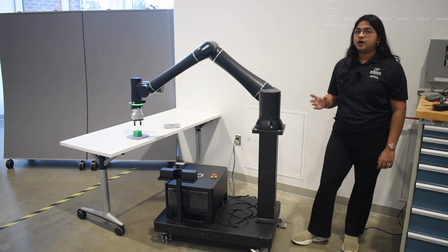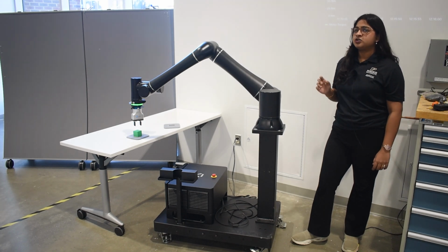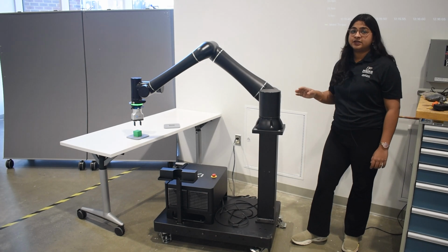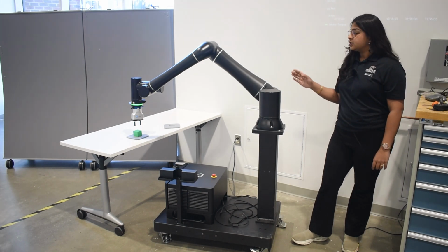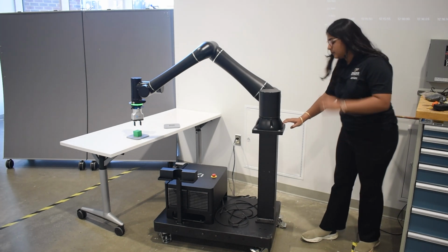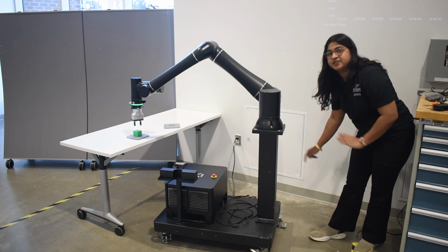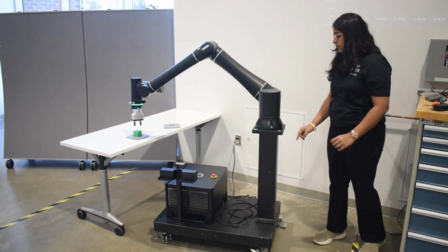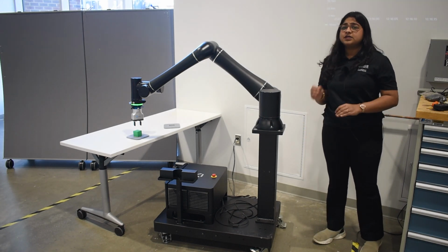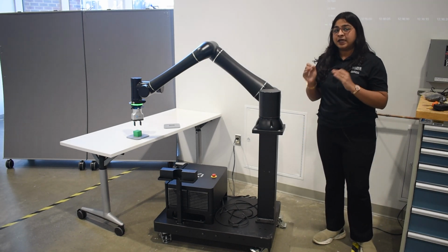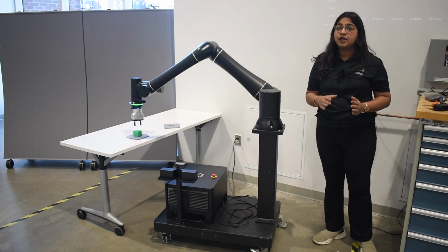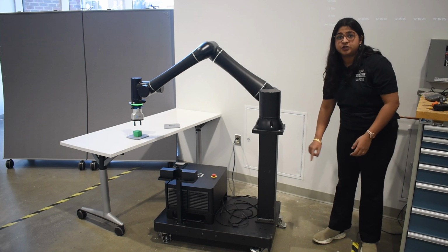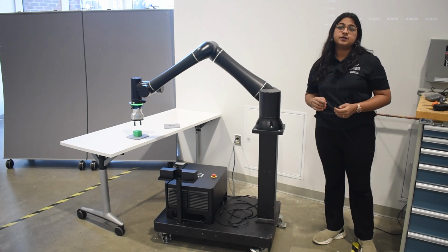Another tip to measure is to always choose one reference point for every object and measure everything with respect to that particular point. For this robot base, I will be choosing this point over here, which is the edge of the base closest to the wall, as my reference point, and I will be measuring everything from that. The reason why this is important is that when you take these measurements into the 3D model, you will be placing the pivot tool exactly at this particular position and moving things accordingly.